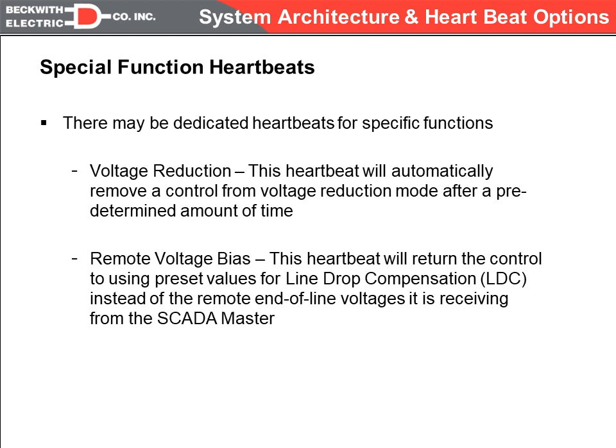So what we can do is have a separate heartbeat for reduction, say 15 minutes. And once SCADA places the control into reduction, it'll stay in reduction for that amount of time and then automatically come out whether SCADA is still polling it or not. And if SCADA wants it to stay in for longer than 15 minutes, SCADA would have to send a new value to that heartbeat before it reached 0 to continue it on.